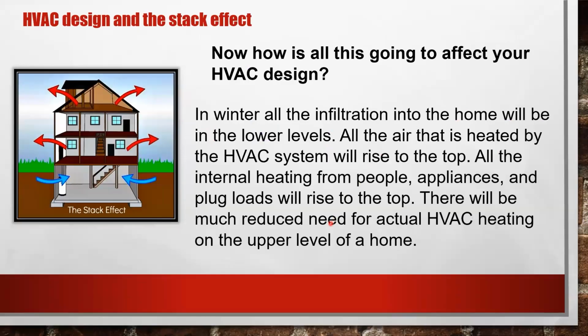So how's this going to affect your design? In the winter, which is our main driver here on the West Coast, all the infiltration into the home will be in the lower levels. There will be no infiltration in the upper levels. All the air that is heated by the HVAC system will rise up to the top of the structure. All the internal heating from the people, appliances, and plug loads will also rise to the top of the structure. Therefore, there will be a much reduced need for actual HVAC heating on the upper level of the structure.